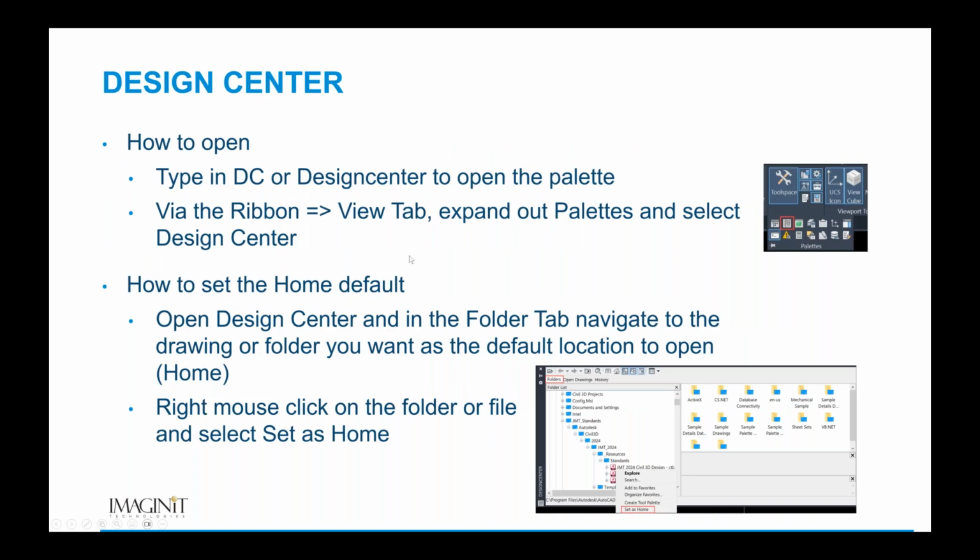So how we do this, we type in DC or Design Center to open the palette. You can also go to the ribbon, View tab, expand out the palette section here and select Design Center.